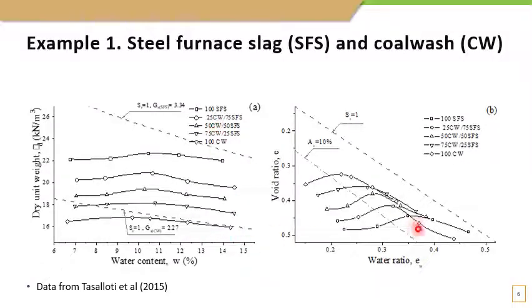But despite that, you notice that the degree of densification, that means the pores in the mixtures, is actually better captured in this new representation. Furthermore, in the conventional representation, dry unit weight and water content, the compaction curves are relatively flat. However, when you use void ratio and water ratio, the curves tend to illustrate the typical compaction behavior you would expect, a kind of bell curve.